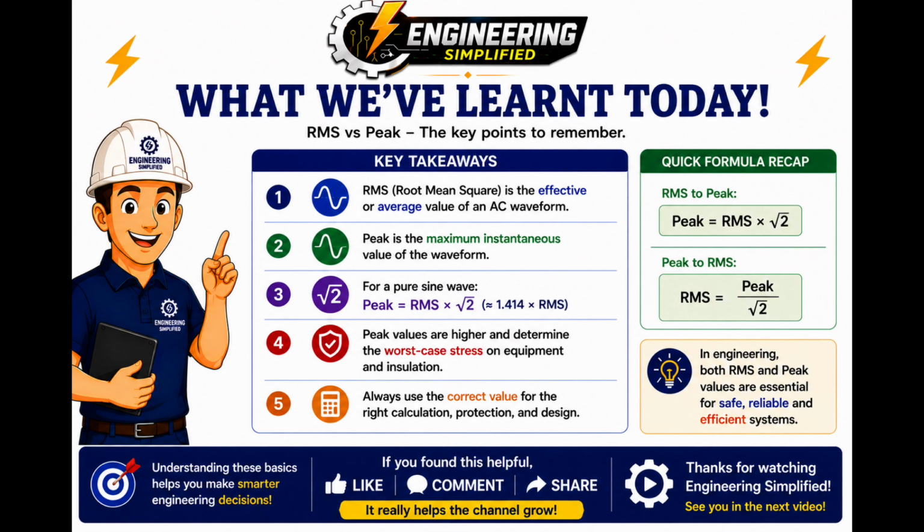So what have we learned today? RMS, or root mean square, represents the effective value of an AC voltage or current. Peak represents the maximum instantaneous magnitude reached by the waveform. For a pure sine wave, peak equals RMS multiplied by the square root of 2, or approximately 1.414 times RMS. And to convert peak back to RMS, divide by the square root of 2.